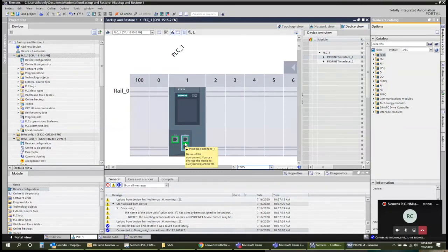So it's intended to be Profinet, and it's intended to have a whole lot of bandwidth, so it can support lots of Profinet nodes, IRT, isochronous real-time communications. This second port, interface 2, doesn't support IRT. It does support Profinet, but usually less nodes. So it's just less computational horsepower dedicated to that port.